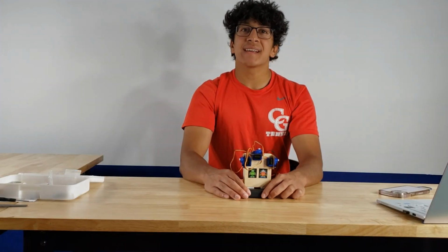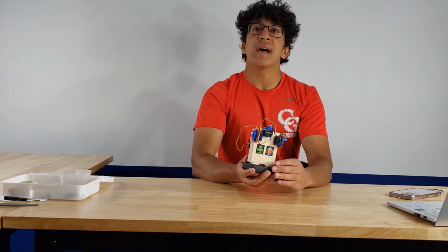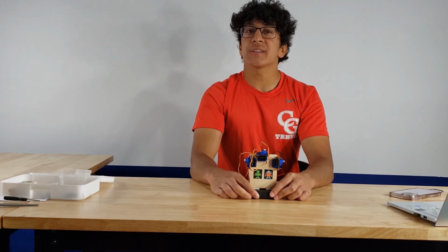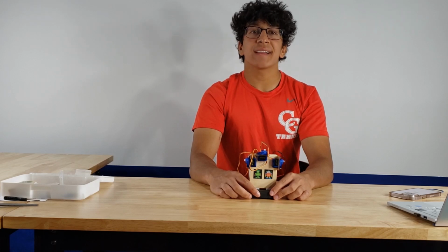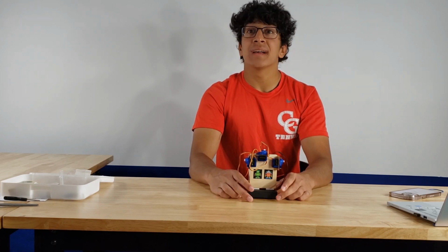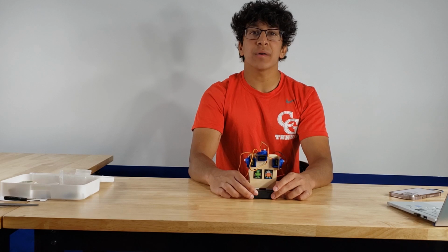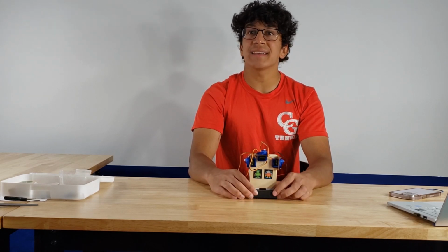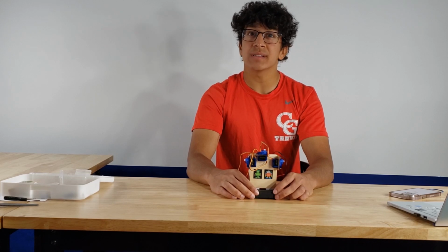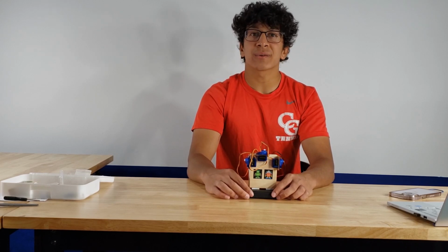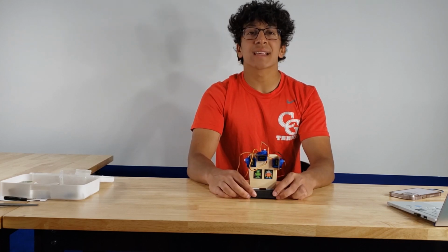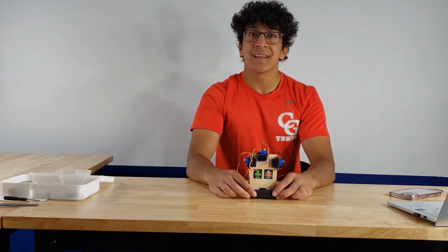In the previous lesson, we installed the microcontroller unit, the motors, and the battery for the robot. The robot is partially done, but we couldn't attach the arms and the head yet, since we don't know what position the motors are in. If we attach the arms without locating the exact position of the motors, the arms may not function correctly. They may swing backwards. So we must calibrate the robot.